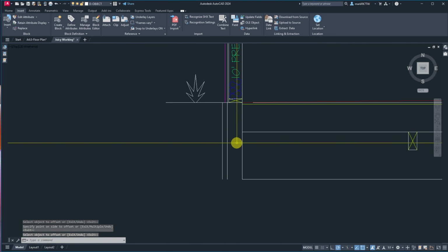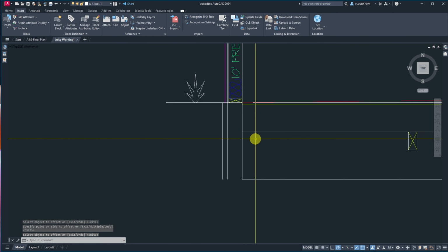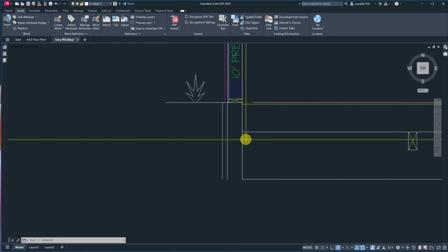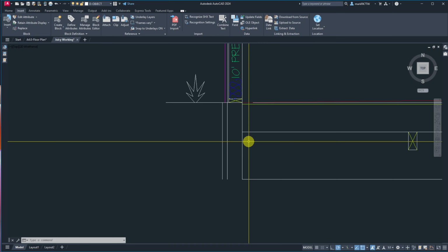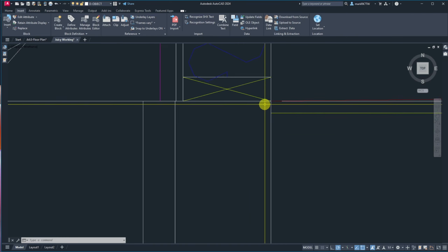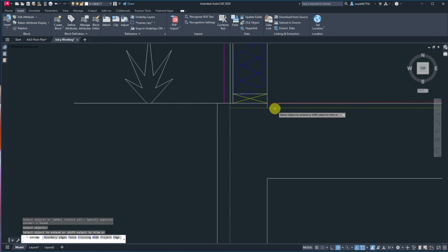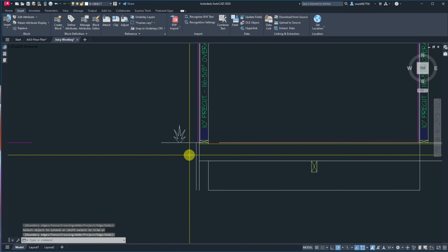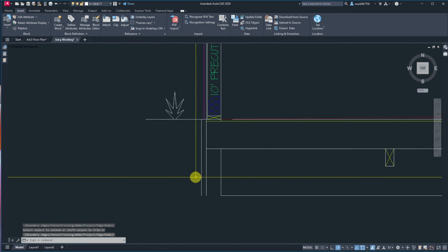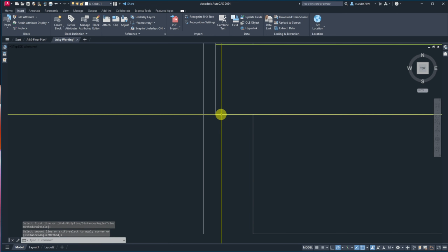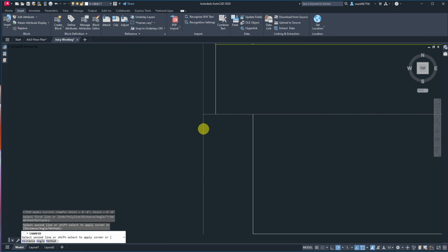And let's set these on top. I can't. Yeah, I can. I have to figure out how I'm going to, but yeah, I kind of have to. So let's trim this out there, extend these out to here. And we'll mirror that around eventually. And then what I'm going to do here is chamfer that to there, and then chamfer this to become an 8-inch block.